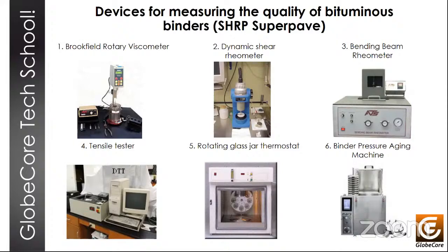On the road surface at low temperature, bituminous binders are subjected to stretching. In this regard, one of the criteria for assessing crack resistance is their deformability at low temperatures. As a result of the test, the temperature is determined at which the specimen tested in tension at a speed of 1 millimeter per minute breaks, when deformation, relative elongation actually, is not less than 1%.